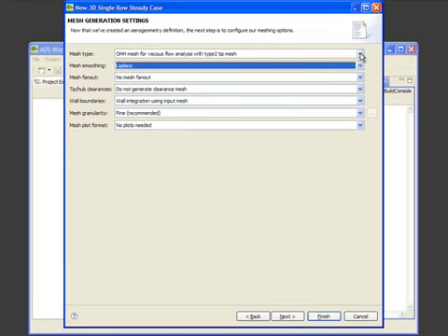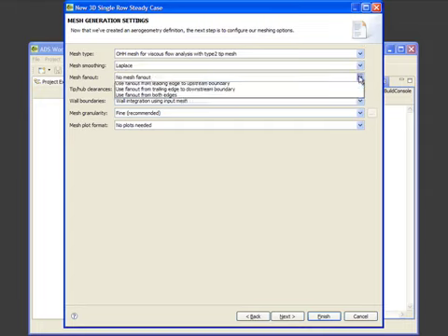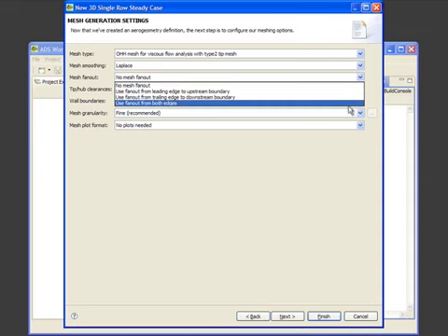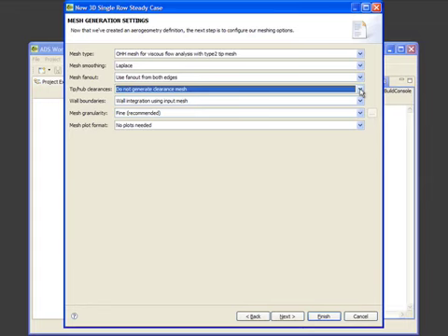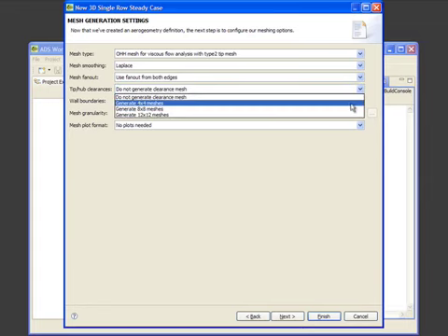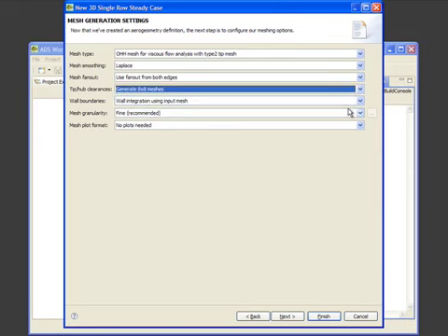For our sample case, if we move down, we're going to use a mesh fan out on both edges. And since we have a tip clearance, we will generate a tip mesh. Here we recommend 8x8, as again, it's a combination of performance and accuracy.